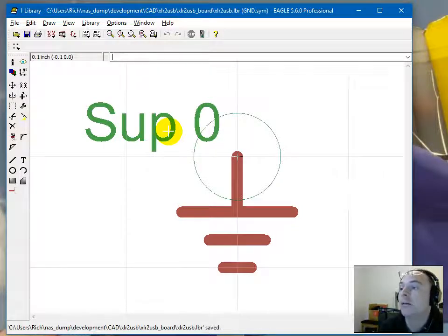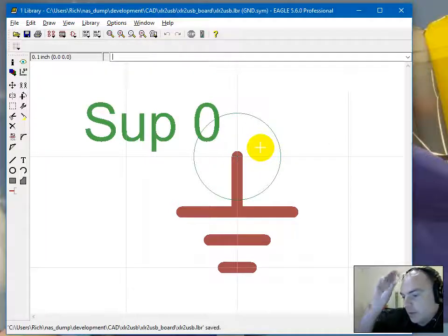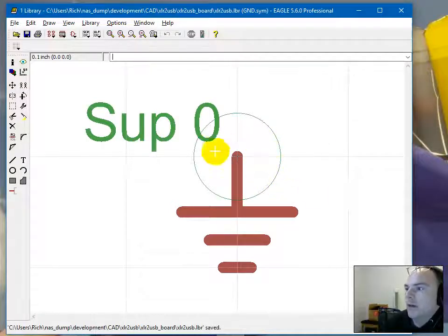Okay, so we have created 3 new parts that are schematic only parts. They don't have bill of materials. Sorry, they don't have footprints. So they don't represent anything particularly useful. We showed how to copy and paste from other libraries so you can bring them into a single system. And we also showed some interesting things about supply nets, right, which have globally shared names.